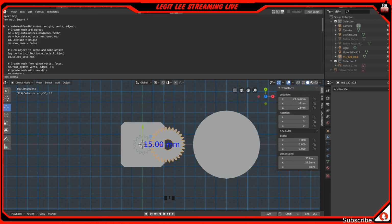And we leave everything else the same. The pivot, the profile shift, all that. The pivot point is going to be the same. Everything is going to be the same. Angle pressure is still 20. We're all good. So if I hit calculate, error, number of teeth 2. Oh, there's none. So 0. Calculate. There it goes. I didn't need another gear, so you have to type in 0 for the teeth for the second gear.